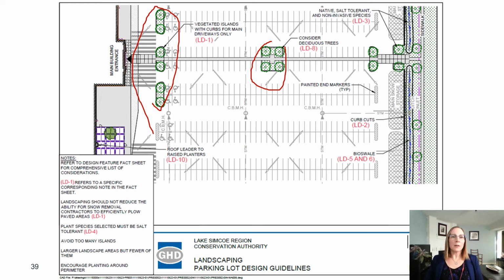And then you can also use your bioretention features to collect runoff from roofs and canopies, but combined with other upstream salt reduction design features to improve water quality. And then the final consideration is if you do want to include vegetation that's not necessarily salt tolerant, you could use raised planters to protect the vegetation, and then that way you're not replacing your landscaping materials every year.